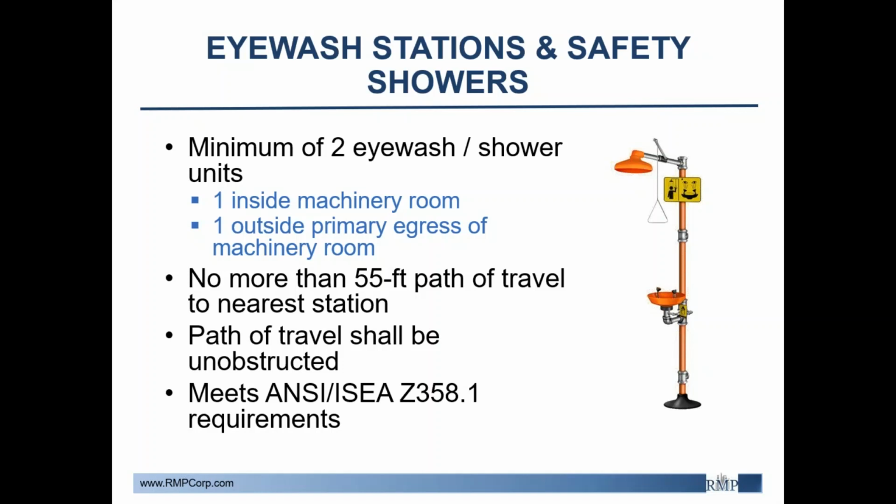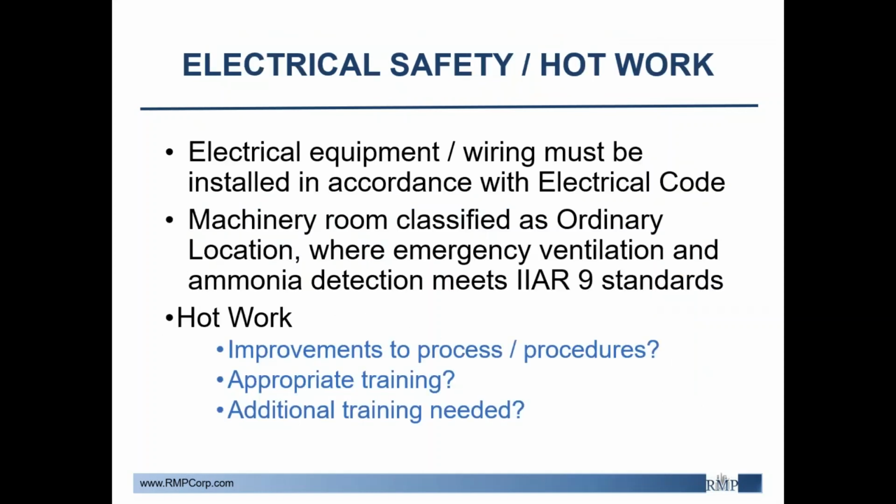There's also, again, arguments for a buddy system on this one for this reason, to get you to that eyewash or shower if you become succumbed or if you are exposed to ammonia or it may get in your eyes and you can't see where you're going. And there are other ANSI requirements surrounding this, so that'll vary a little bit facility to facility, but generally speaking, these are the minimum requirements.